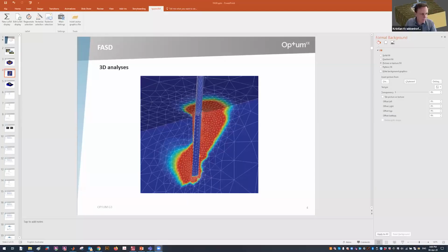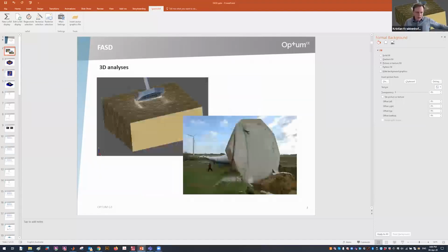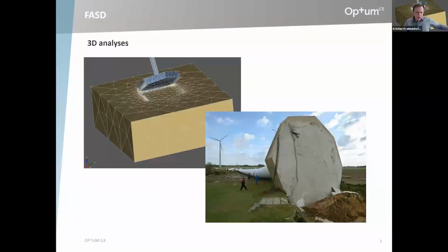There weren't really very many slides to do with initial words there. What I wanted to show was some typical 3D problems where you are faced with this question of what friction angle you should pick: the one representative of biaxial, say plane strain, or some other friction angle representative of other stress states.